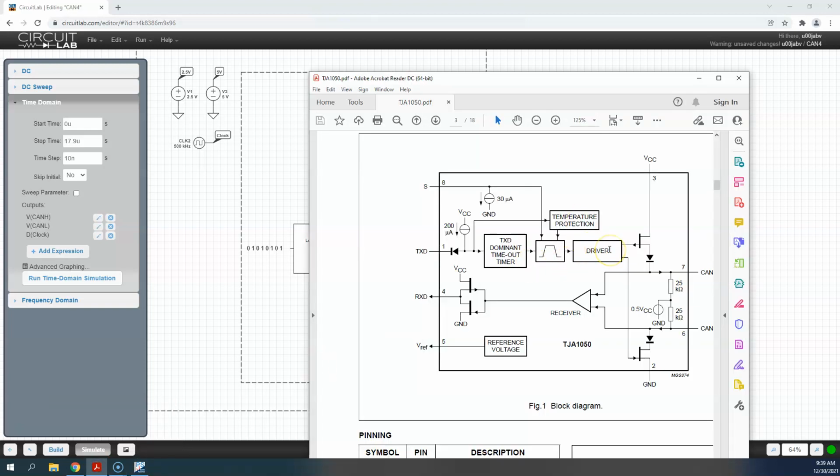So this goes back to our schematic of the CAN transceiver, the block diagram. We've added these high side and low side drivers, and then some logic here is going to cause this driver to turn these high side and low side drivers either on or off, and they would both happen at the same time because we need to provide the 5 volts and the ground at the same time. If we don't, then it's going to cause an offset on the signal, and we'll look at those as one of our failures.